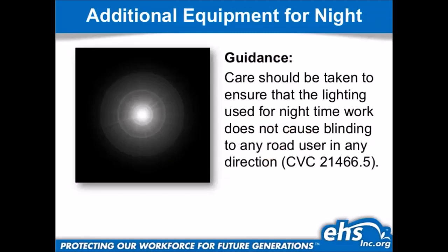How you're setting up the lights matters as well, the lighting. It always has to be set up so the people driving by can see you, so you can see what you're doing, right? So it should never be aimed towards traffic. It should be aimed towards the work site.